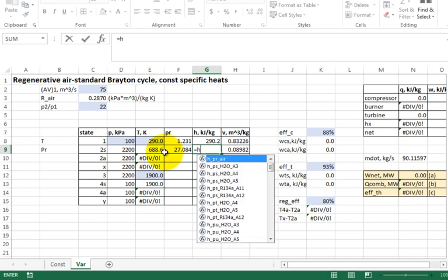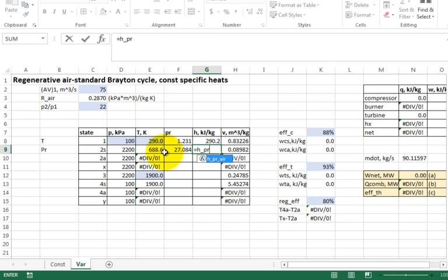And then this is the enthalpy as a function of PR for air, and there you go. So I have my enthalpies. Now, I come over here and I say I'm going to still use this efficiency, but this time I'm going to calculate the work that the compressor would consume if it was isentropic compression. I now have my H's, so I come over and I say, well, it's that H minus this H, isn't it? H2 minus H1. I don't need that parenthesis, do I? Delete that. Backspace, there we go. Right? And then, using this efficiency, isn't the actual work there?